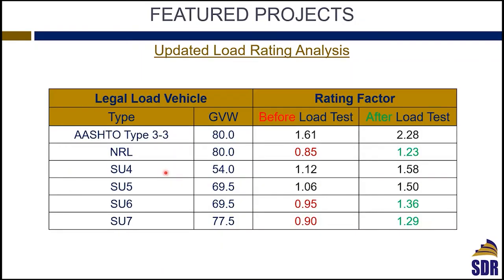Again, based on just what we could develop as some negative moments at the end of the beams, you can see that your load rating was 0.85. Now you can go up to 1.23 easily, just by accounting for some of the negative moment that you can develop at the end of the beam. In the same sense, it is unfair for that bridge to be load posted, given that it has a lot of strength and redundancy in the system that can take loads much more than what we estimate based on design codes.